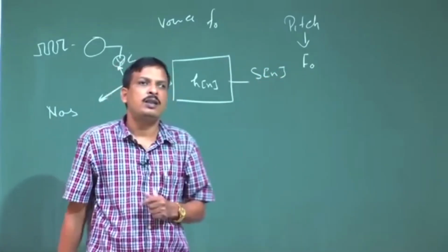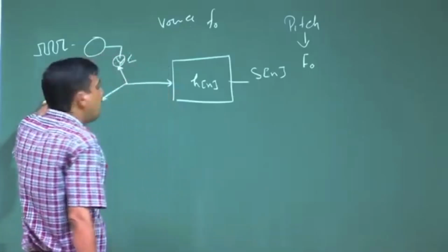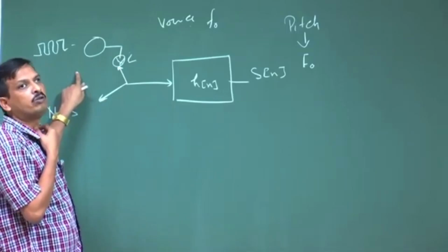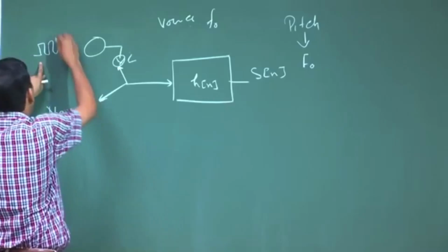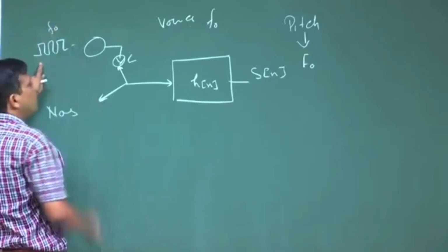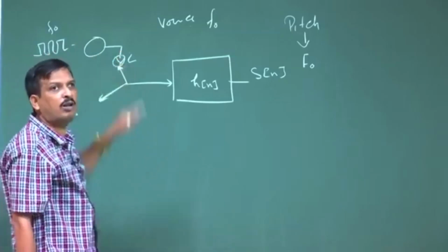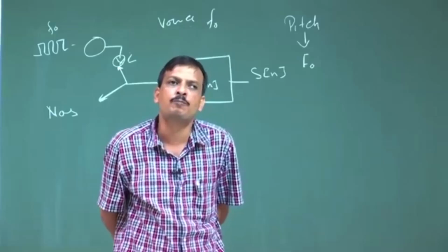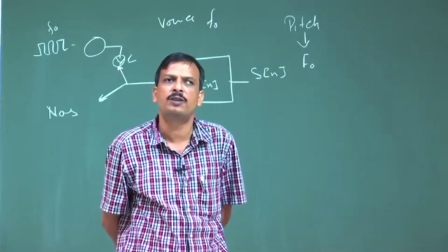Okay. So, now what is F0? F0 is part of the vocal cord oscillation. So, F0 will be here. The impulse by which we are simulating the vocal cord vibration has a period. That period is responsible for the fundamental frequency of the speech signal.